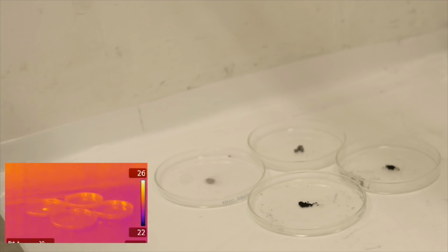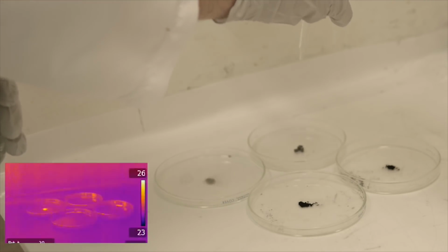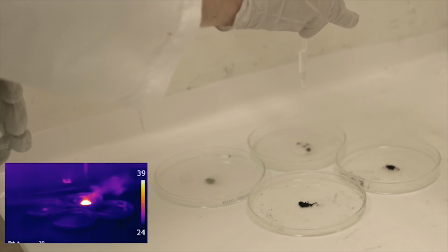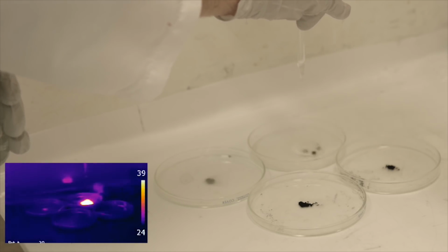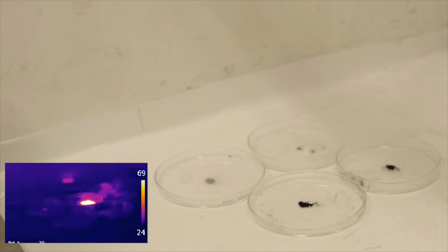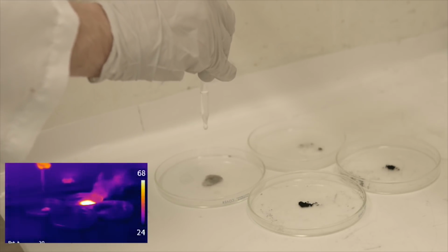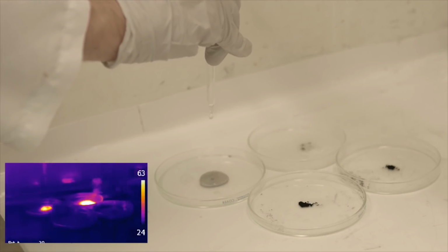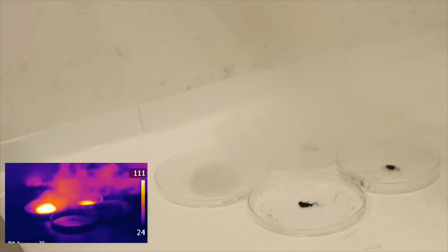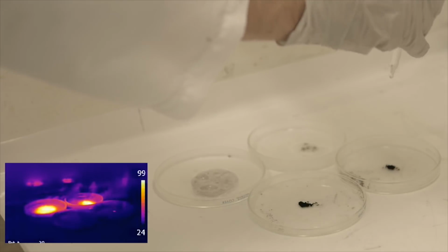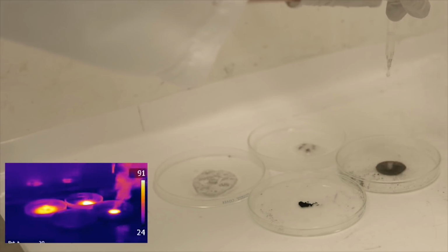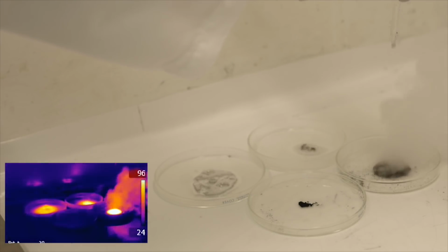So the fluidic-based actuators require pressurized fluid, gas or liquid. And so what we do is we rely on peroxide decomposition. So monopropellant decomposition, in this case hydrogen peroxide, in the presence of a platinum catalyst. And so it's a very energetic reaction, and I can tell you about the kinetics of this later, but nonetheless, the products of this are hot gases basically that are useful to power whatever fluidic actuator you want downstream.